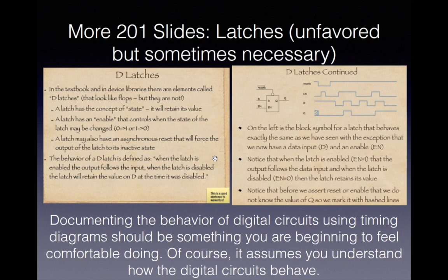We may have a reset into a latch. And what I paused for, I wanted to say that this is why we call a latch, a D latch, a transparent latch. What that means is that when the latch is enabled, what's happening on D passes right through the latch and happens on Q. You can see that here, and I know that the pointer device doesn't always work.